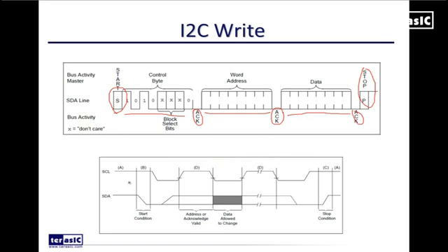Now, what do I mean by start and stop? If you look to the bottom over here, we have our start condition, which is basically when the SCL, or clock, is still high, the SDA, or data line, goes low, and the clock then goes low. Then we can start our data and address communication. That's known as the start condition. The end condition or stop condition is also very similar, where the SCL or clock signal goes high and the SDA goes high as well.